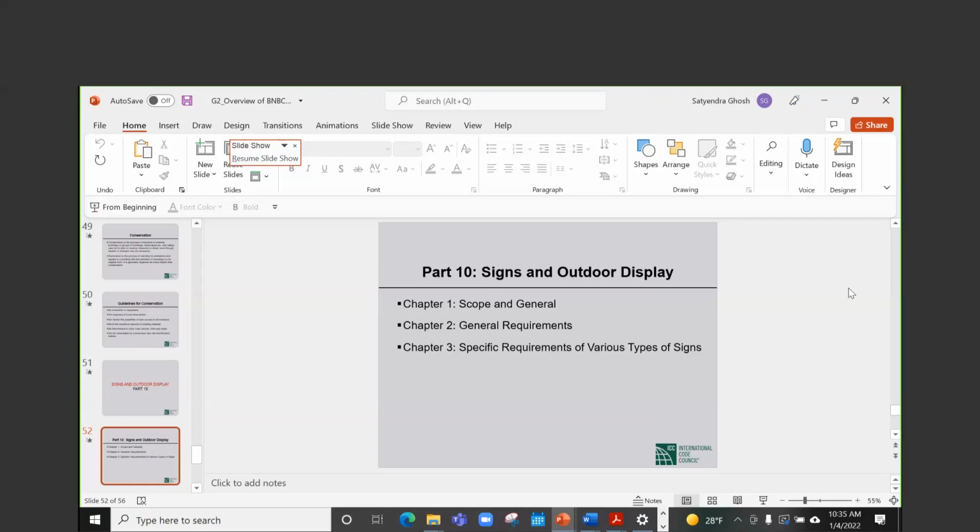Why part is very clear. Reduction of live load: the idea is if you have a large area, it is extremely unlikely that the entire area will be loaded with the full design live loads. The larger the area, the more unlikely it is. So the larger the area, the larger the reduction we take on the design live loads.